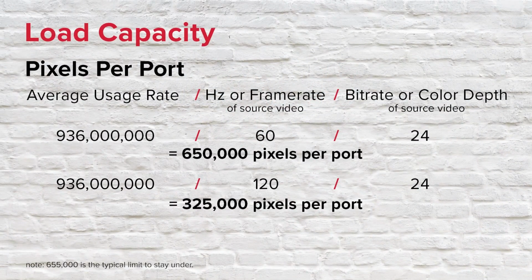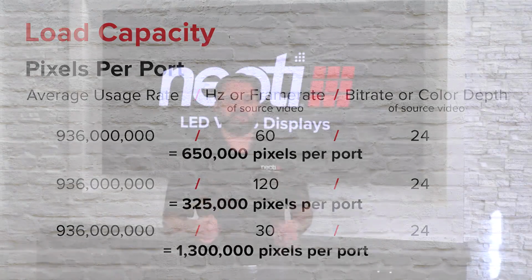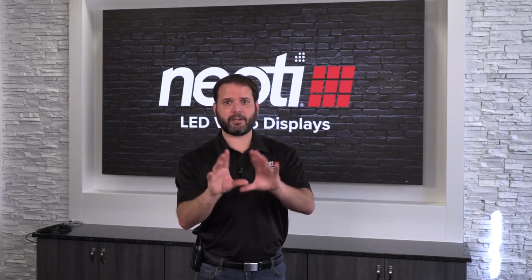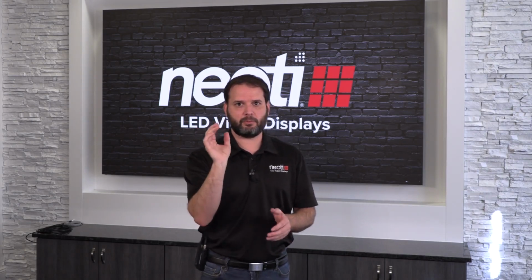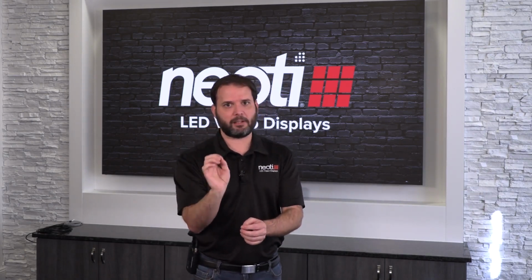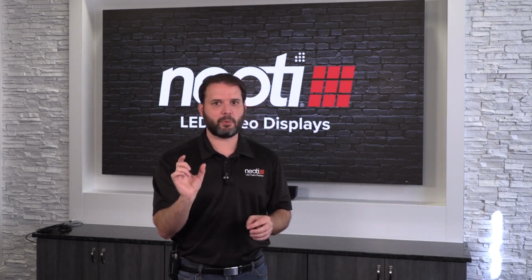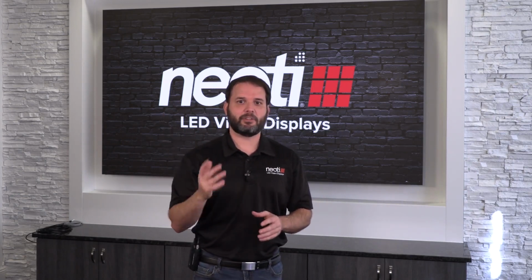Alternatively, if you want to only run everything at 30 hertz instead of 60, then 655,000 actually doubles, and you can run twice the amount of panels that you normally would with the average 60 hertz. And so there's multiple ways to get things done in this scenario. There's multiple ways to drive different panels with different amounts. If you have a limit on ports and you can't get another controller, and you have to drive that many panels with just a few ports, then you can absolutely do that. But the compromise is you have to knock it down to 30 hertz.